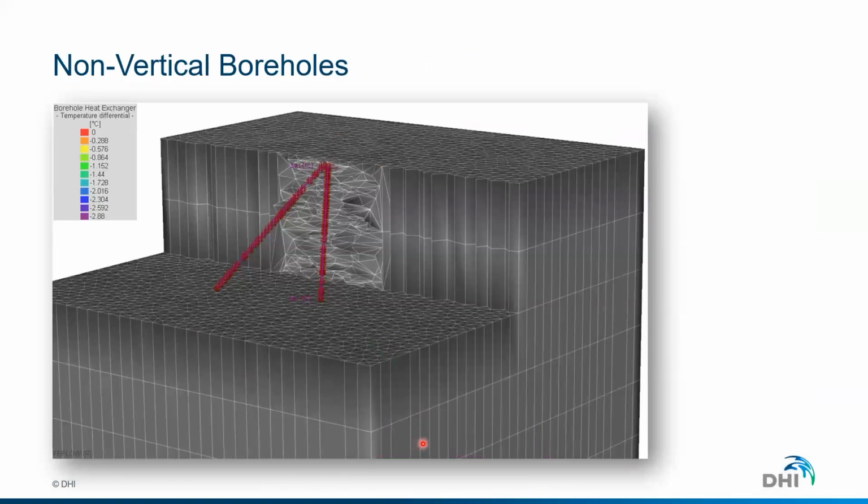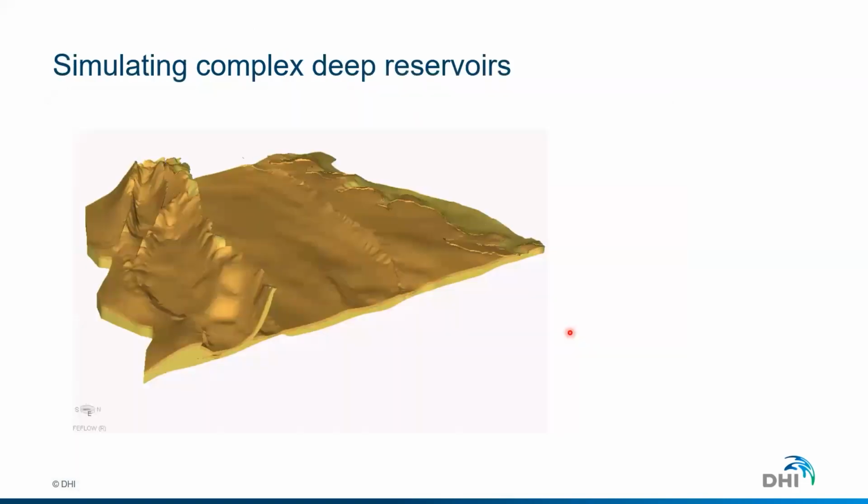The second advantage is that you have a very good way of discretizing around the area of interest. So if I will be focusing on this area, I want to have most of my finite elements located here to be able to capture all the different processes in detail. In areas which are apart from the interest, but I still need to model because I would like to investigate the impact at the regional scale, I could use large elements for the calculations.